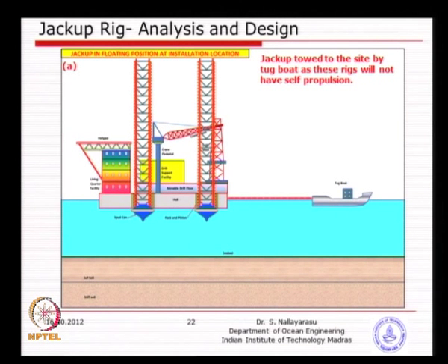Basically none of the jack-up rigs have propellers, so they cannot come on their own. 99% of the time you will have to tow by tugboats, and tugboats of sufficient pull capacity, because you are going to come from several thousand kilometers. So, at that time you want to make sure that the legs are not penetrating downwards into the water.